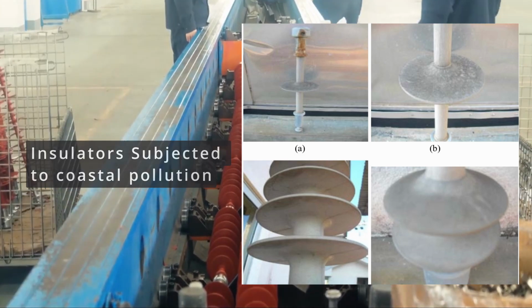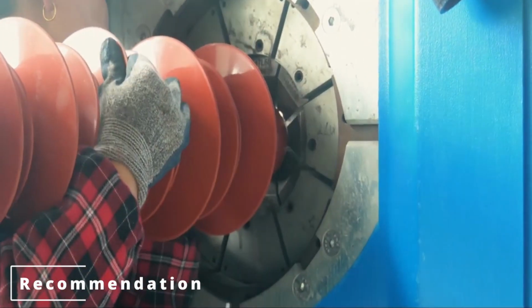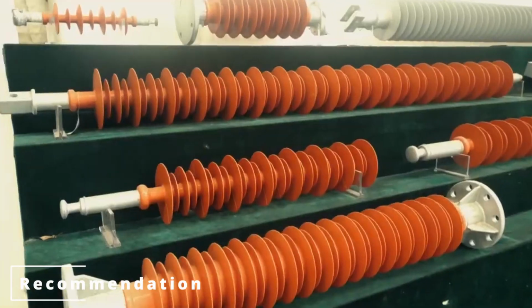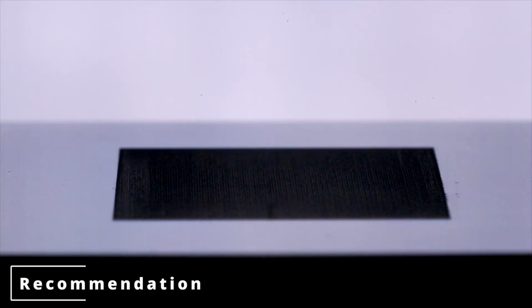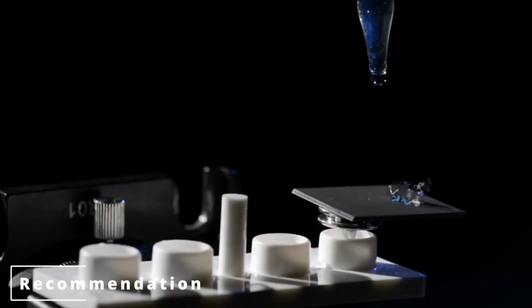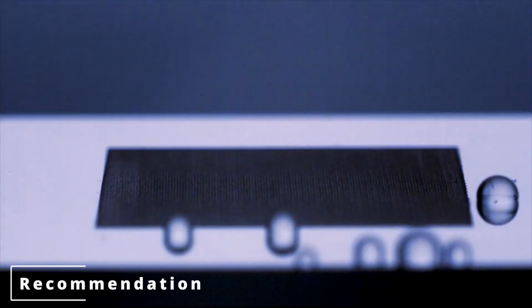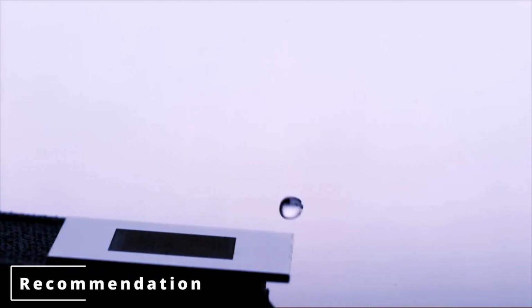The results of the study can be utilized by the manufacturing industry of polymer insulators. In practice, insulators with very high hydrophobicity are preferred in order to avoid water droplets accumulating on the insulator surface. Achieving a high hydrophobicity would be costly. According to this project, Scenario 3, which represents a more practical situation in the field where the insulator is subjected to pollution effect, shows that to mitigate the E field stress along the insulator, the water droplets must be at moderate contact angles. Here, even though for low contact angles the E field values are minimum, it is not practically recommended because there is a possibility of a group of water droplets with lower contact angles forming water films on the insulator.